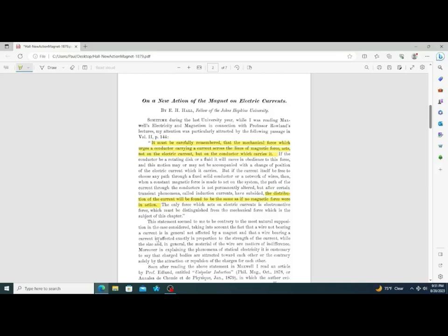You just take a permanent magnet and it sits there without moving while that current's running through that gold leaf. You take a voltmeter, put one probe on one end of the gold leaf, the other on the other end, and you get a voltage difference. And if the magnet's north facing, you might see a positive voltage. You flip it over, now it's a negative voltage. So that's the basis for the Hall effect sensor.